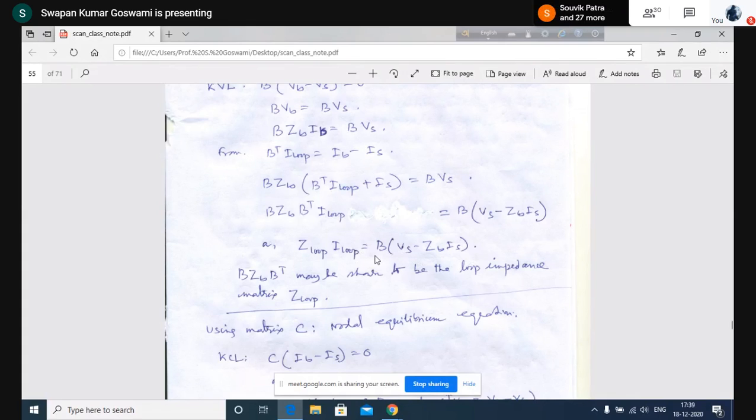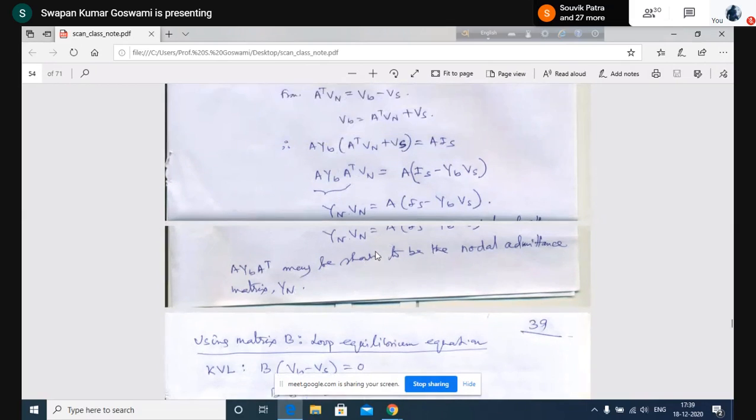Very easily. In the same way also, you can write this expression. Then you can form this matrix, this product, the nodal admittance matrix will be obtained. Then obtain the node voltages as the inverse of this matrix multiplied by this one, you will get the node voltages. Once the node voltages are obtained, from that you can find the element voltages.